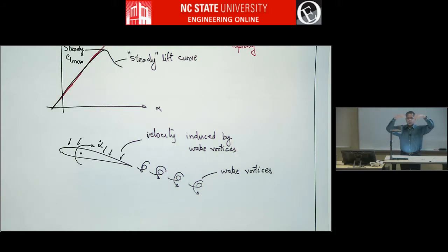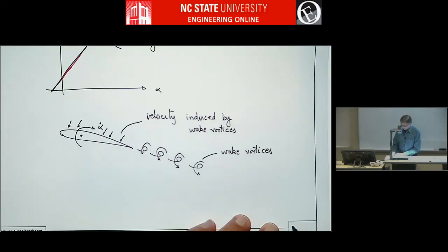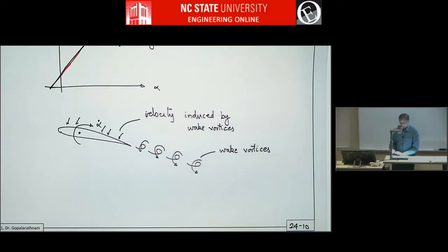But when there is downwash, the boundary layer stays attached to a higher angle of attack and has higher lift, higher CL, and at some point even with this downwash, the adverse pressure gradient becomes large enough, and the boundary layer will separate. These are the sort of things my group is also studying a lot. It's pretty fascinating.